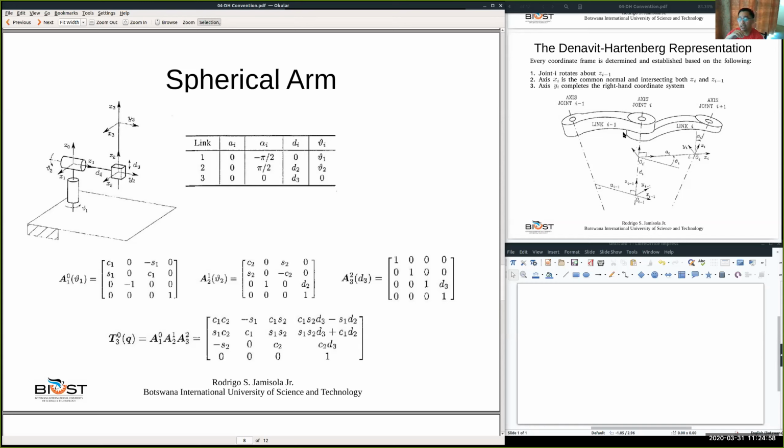In this case, it has 3 joints, and it will be able to point to or locate all the points in the sphere as a solid sphere, compared to looking only at the shell of a sphere. If you want to draw a shell of a sphere, it will be similar to a pan tilt joint. Pan tilt is that one joint rotates and the other one only tilts. So it pans and it tilts.